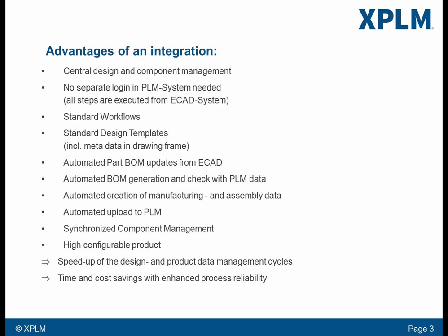Workflows are automated. For example, the generation of the bill of materials, a consistent check of it with the data in PLM, the generation of the PCB and pick-and-place information, and the transfer of those data to the PLM system are included. Also, the synchronization of the component information between the development library and the product lifecycle management system is a very important issue.